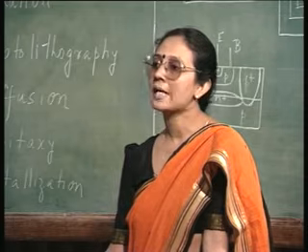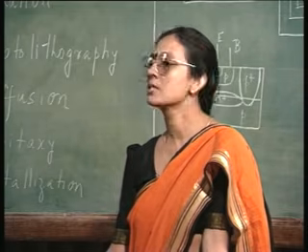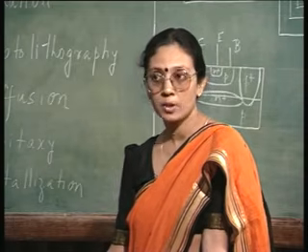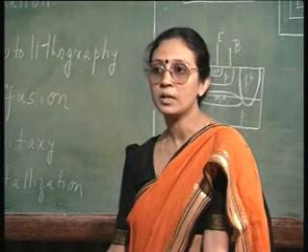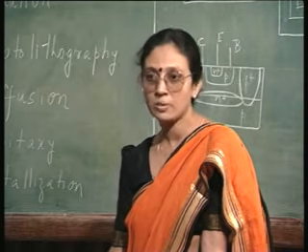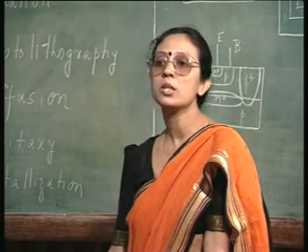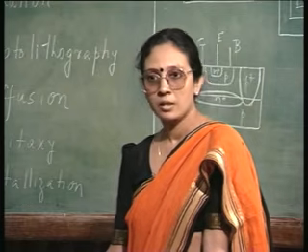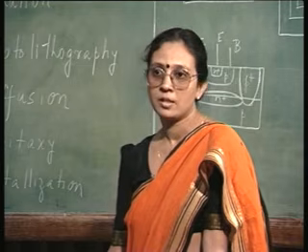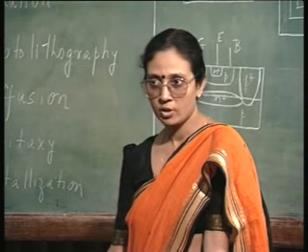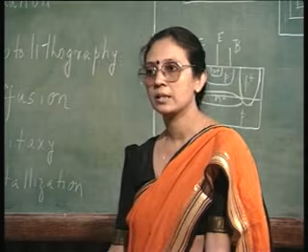So, to take contact from an N plus region is not a problem. The only problem is to take contact from a lightly doped N region. That is why I said, in order to facilitate collector contacts, we use an N plus pocket.